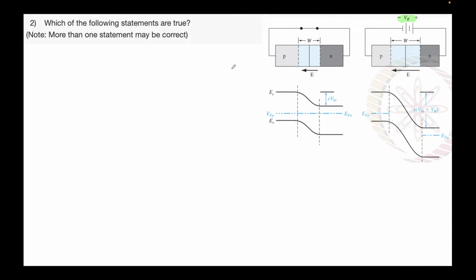In the avalanche breakdown, this arises when we bias a p-n junction diode in the reverse direction. So this is the unbiased p-n junction. You can see the Fermi level is flat, and there's some built-in potential voltage. When we apply a negative bias VR to this p-n junction, you can see that the depletion region is widened as compared to the unbiased one. This is the reverse bias. It has widened a bit, and you can also see the electric field has increased in intensity. It's denoted by this longer arrow of the electric field E vector.